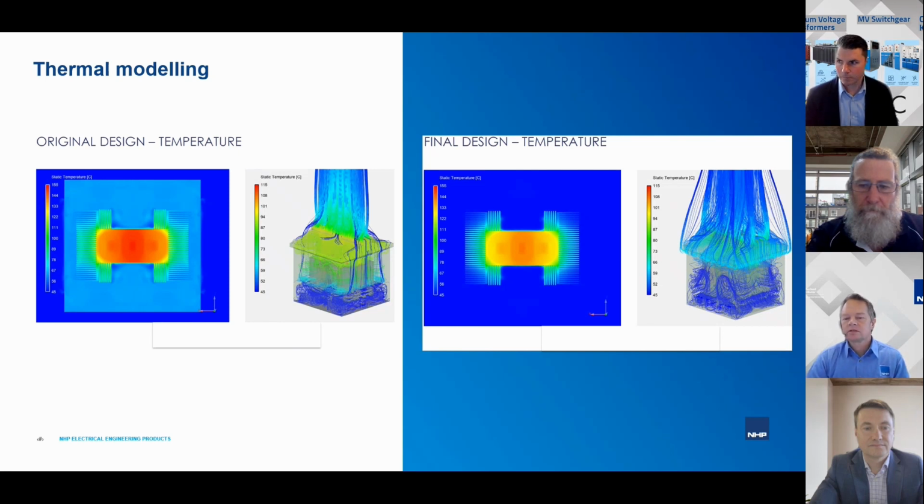With the right-hand design, with that knowledge, we can look at how we can improve the ridge vent design. So we've improved that ridge design. We've had a better laminar flow, higher velocity. And one of the great things about thermal modeling is, you don't always just see the direction of the air, but you can see the velocity of the air, so the actual speed of it. Obviously, velocity is direction and speed.